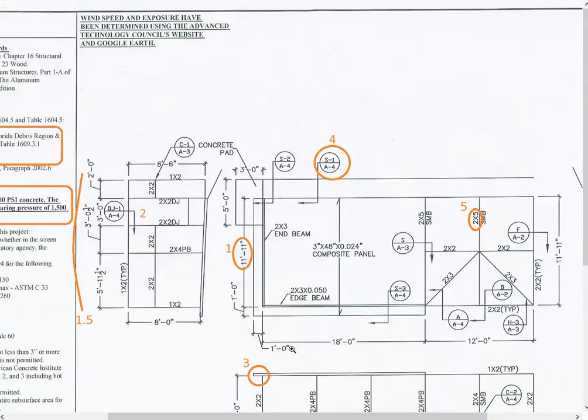Let's move on here to number 4. Okay, number 4, you'll see a bunch of little details here, little numbers and symbols and stuff, and this is S1A4. This references a connection detail and what page it's on. These engineering diagrams often have 3 to 7 pages, and they're specifying what type of connections must be used. And at each connection, they're going to give some type of indication about how many screws have to be used there, what type of cut must be used there, what type of plates or connection metal must be used there.